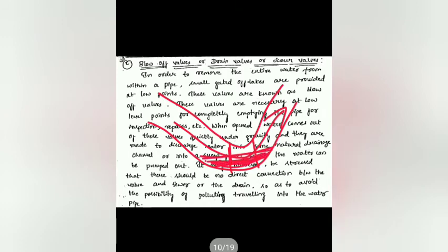So this is a kind of blow-off valve. These are generally provided at low levels, like this. At these points it is sometimes very difficult to drain off the entire water. Due to gravity, some amount of water remains at these lower points. During the repairing process, we have to completely empty the water. That is why blow-off valves can be provided at these points. That helps in case of repairs, and also helps in draining out the complete water when the valve is opened.